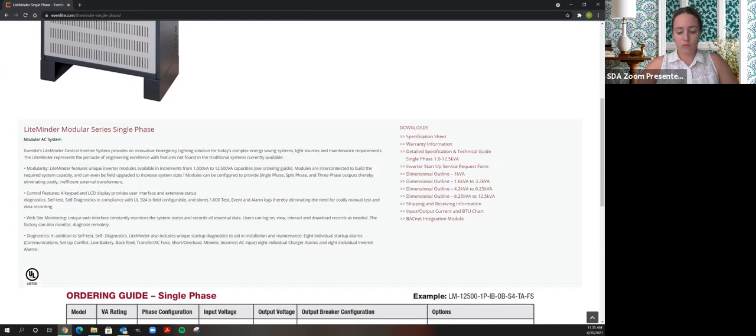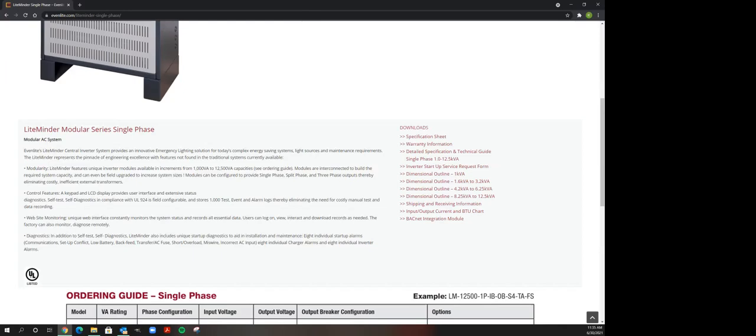And really, when it comes to batteries, you really don't want batteries sitting around for a long time. That's every battery manufacturer or inverter manufacturer. You don't want the batteries sitting around for a long time because the batteries do need to be top charged within 6 months.